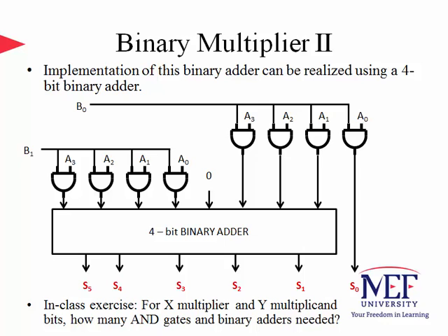A 0 bit in the first 4-bit input to the binary adder is needed because of the inherent shift of the multiplication operation. Recognizing such a shift in multiplication rings the bell for alternative implementation techniques for multiplication. For example, one potentially less area-consuming implementation would be based on sequential logic, where the shift operation can be handled by flip-flops. Such circuits will be covered later in the class when we analyze and design sequential circuits.